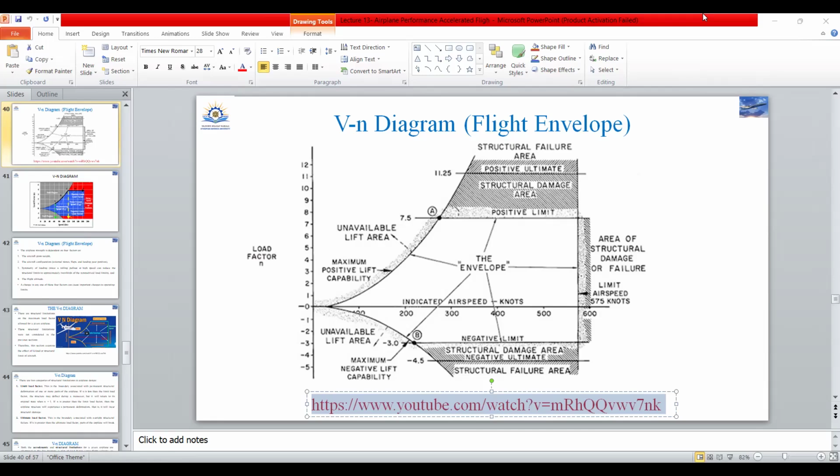This point is called the maneuver speed of the aircraft. This is because, below this speed, there will be no structural damage to the aircraft while performing different maneuvers. This region is called the safe envelope of the aircraft. The aircraft must be operated within this envelope to prevent any structural damage. In modern aircraft, because of fly-by-wire technology, protections are provided in the auto-flight system, which do not allow the aircraft to exceed this safe envelope at different speeds and configurations.